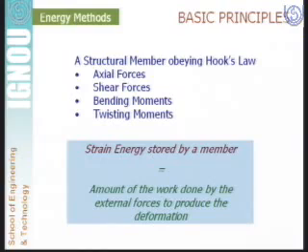I will give you the concept of strain energy. If any structure is linearly elastic, it obeys Hooke's law, and if any force or system of forces are applied to the structure, then strain energy is stored in the structure because of the axial forces, shear forces, bending moments and twisting moments. This is because of the elastic deformation inside the structure. So that's why we say that energy is stored in the member.